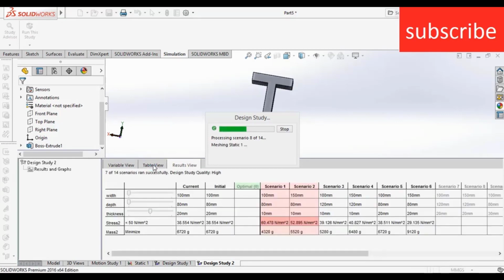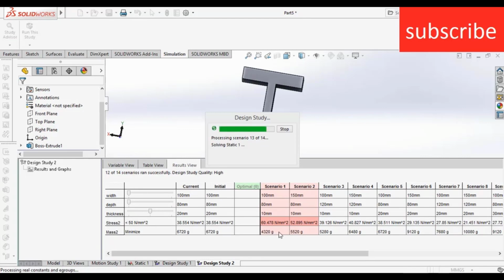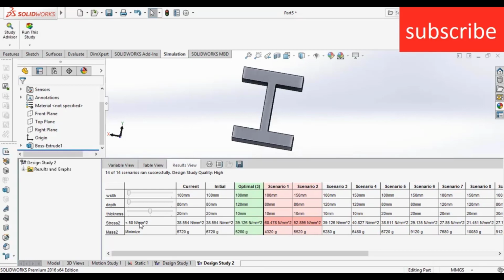Okay, I can't go back to show you. So it is running within the variable range, and here you can see where it is basically crossing my constraint. The red part is basically where stress is greater than 50 newton per mm square. Because of that, it shows them red, because these results are not ideal or beneficial for me. They also contain less mass, but they are not going to be recommended because they exceed the limit of 50 newton per mm square.